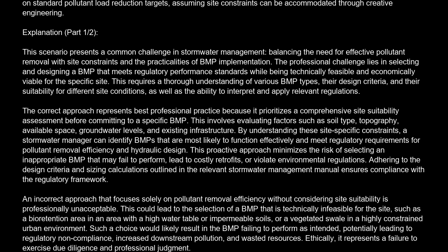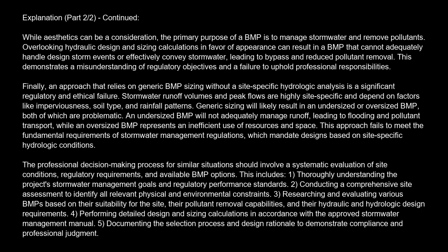Another incorrect approach that prioritizes a visually appealing BMP over functional design criteria is also professionally unsound. While aesthetics can be a consideration, the primary purpose of a BMP is to manage stormwater and remove pollutants. Overlooking hydraulic design and sizing calculations in favor of appearance can result in a BMP that cannot adequately handle designed storm events or effectively convey stormwater, leading to bypass and reduced pollutant removal. This demonstrates a misunderstanding of regulatory objectives and a failure to uphold professional responsibilities.